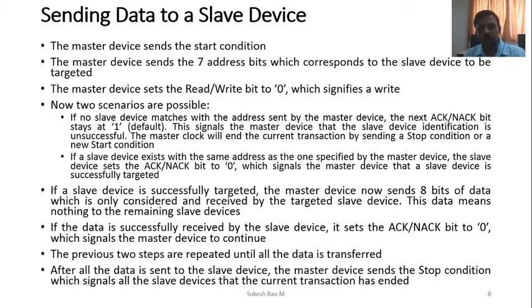Since we are writing to the memory, every location is treated as an address, and from that address onwards the data will be written. Maybe you are writing to a register, maybe an hour register, minute register, second register in an RTC. Then you want to address which register you want, so you need to address that. The next is the slave address to be targeted.